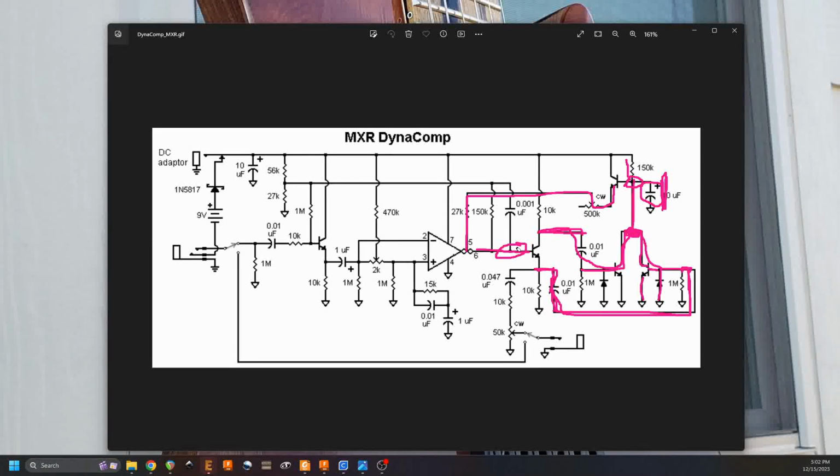Now, those two circles can be a little confusing, but the thing to know about an operational transconductance amplifier is that where it shows those two circles, that is actually a control current point, meaning that if we apply a current onto pin 5 of this chip, if we apply it here to the control current, it will actually reduce the gain of the amplifier.